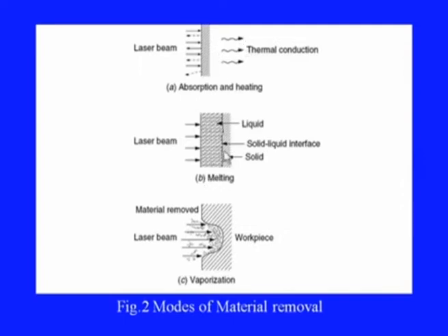On continued application of the laser beam, if we continue for some time, the heated material starts melting. It becomes semi-molten or molten, a liquid state instead of the solid as we have seen in the first case, and the width of the molten zone will increase as we keep on pumping laser energy onto the surface.